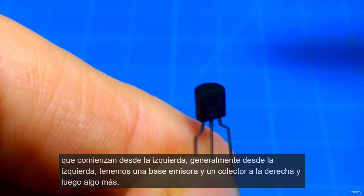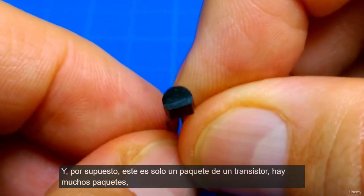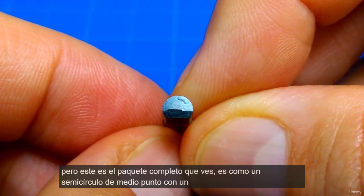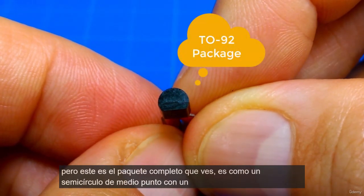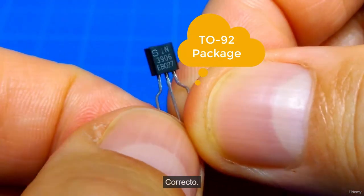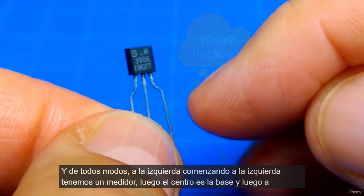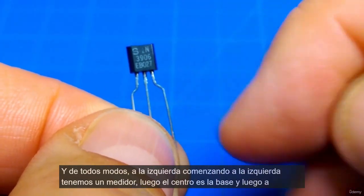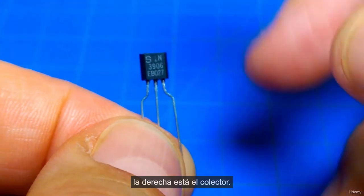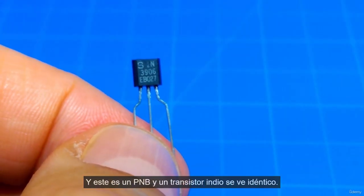Of course, this is just one package of a transistor. There are many packages, but this is the through-hole package. It's kind of a half semicircle with a little bit extra there. Starting to the left, we have emitter, then the center is base, and then to the right is the collector. And this is a PNP. An NPN transistor looks identical.